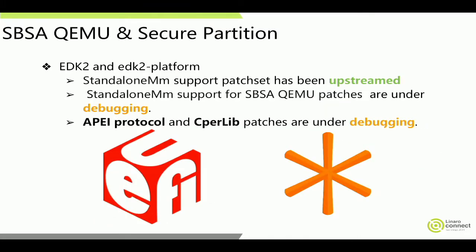Except that, we also need EDK2 and EDK2 platform support. The standalone MM support patch set was upstreamed, I guess, months ago, and the support for SBSA QEMU is under debugging because I hit a problem in Trusted Firmware.